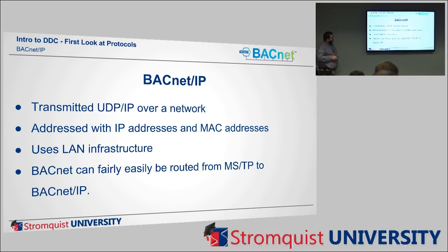And that's wrong. It's addressed with IP addresses and device instances, not MAC addresses. I need to fix that. And BACnet IP can use the building's existing network. A lot of times it's hard to get on a building's network and you have to run your own network. But it does run just on a computer network.